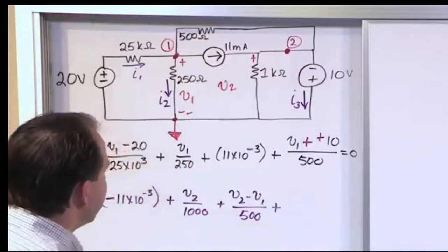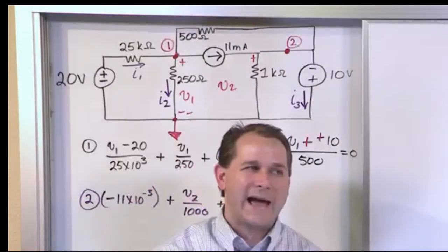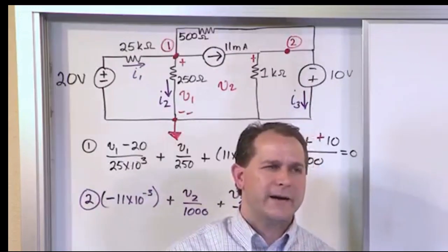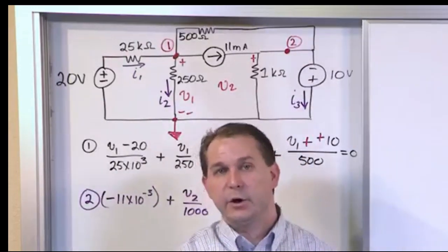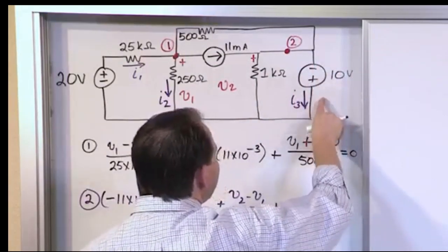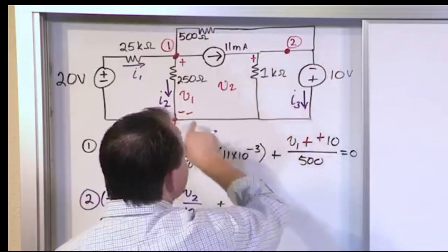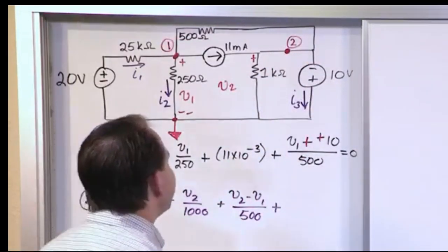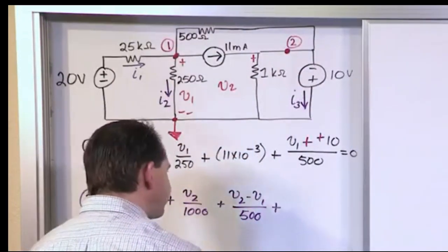So we start looking at this, and we quickly get a little bit stumped. Because typically with node voltage, either you have a current source telling you what the current is flowing in or out of the node, or you have a way to subtract voltages and divide by a resistance, like this minus this divided by 10 ohms, that's the current in a leg. You can't do that here because I need to know what the current is here, but it's completely unknown. I can't pop up to V2 and subtract anything. There's nothing to subtract, it's just there, right? So how do I find the current flowing in here? It's very difficult for me to figure out how to do that. So what you end up getting is stuck.